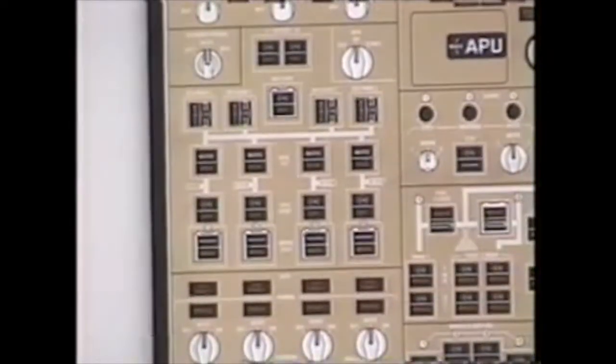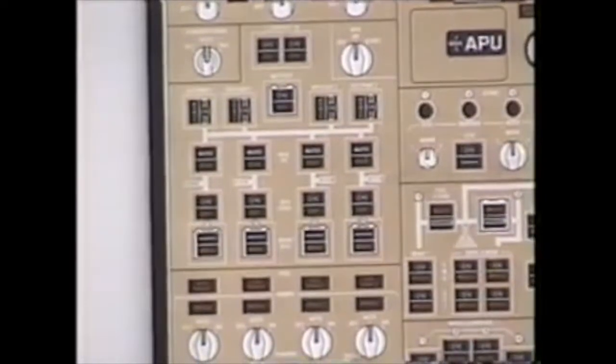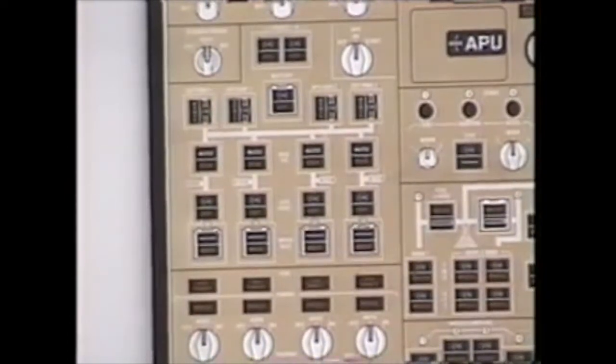To ensure that the system has switched over to the backup power source, it's important to check the 2 battery discharge messages on the primary ICAS. It will then position the switch back to automatic, again making sure that the captain's PFD, ND, primary ICAS, and left CDU remain powered, and most importantly, that your 2 battery discharge messages go away on the primary ICAS.